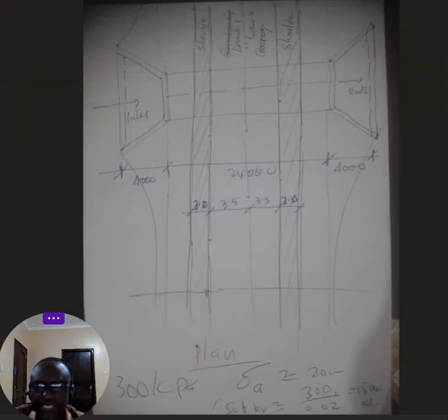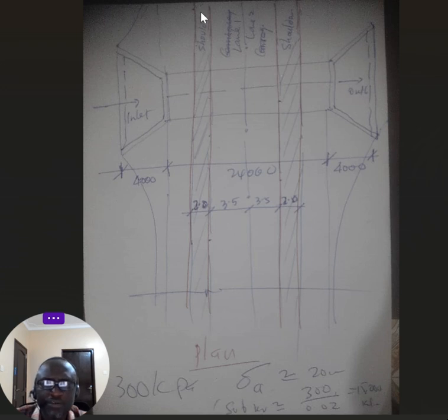Then after the profile here, you need also to know the plan. The plan helps us to know this tapering, the flaring of the apron and the wing walls. You have the shoulders, you have lane 1, lane 2. This total gives you the carriageway, and they're all given in here. You have a soil of maybe 2 meters, and then the lanes are 3.5, 3.5. Now, if you had a bridge, you would have a raised walkway, but for a box culvert, maybe it's made slightly wider and then you're able to get a walk through. But for a bridge, normally you have a raised walkway or marked.